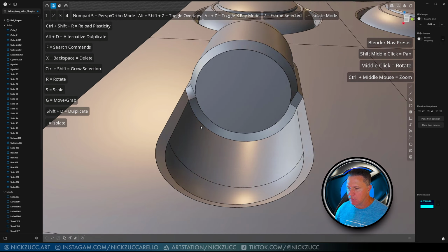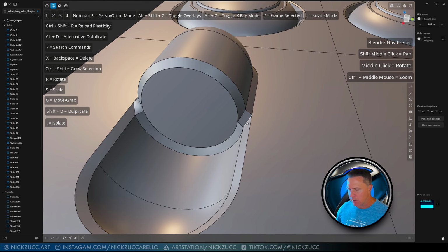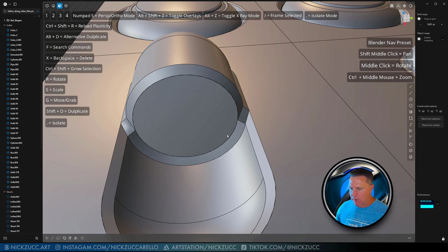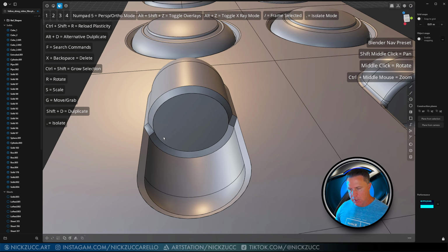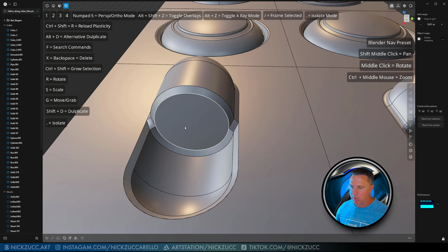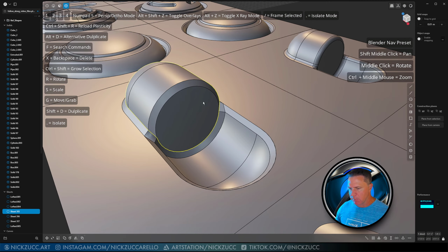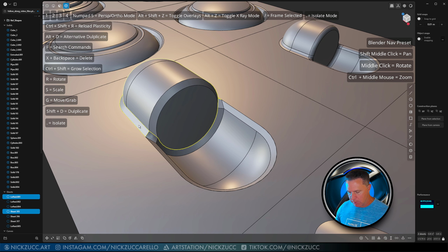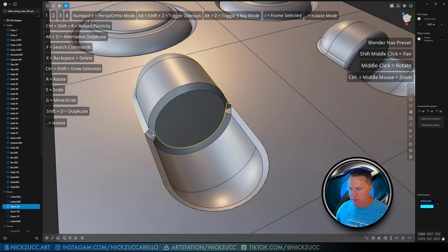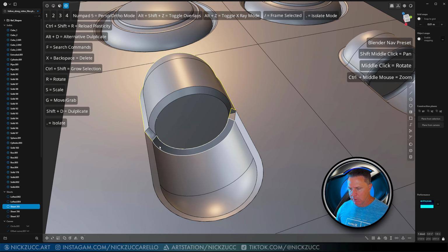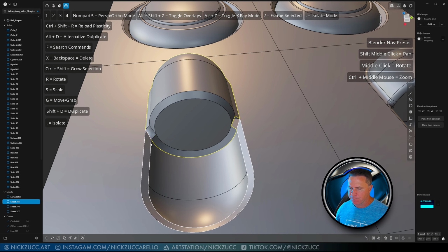All right, so that's one way to get it done. And sometimes you might need to patch things. So let's get rid of this. And what I'm going to do is tap 4, select all these objects, tap J to join them. And if you have trouble, you might want to do these one at a time. So I'm selecting this and tapping J. So it's basically welding these things together.